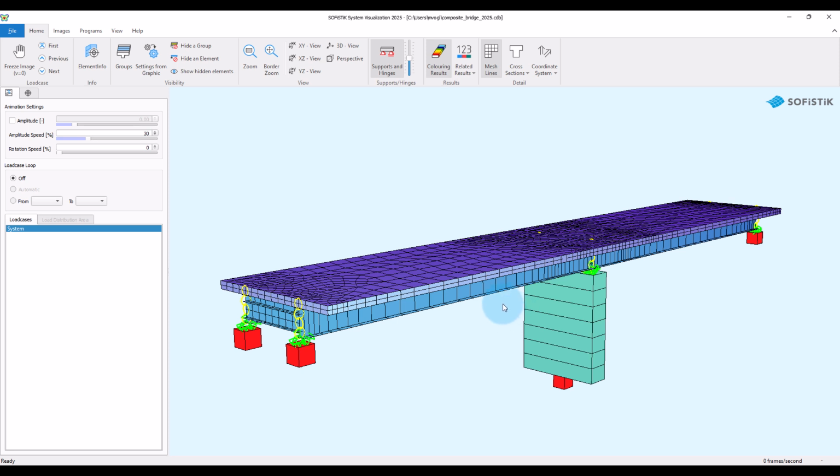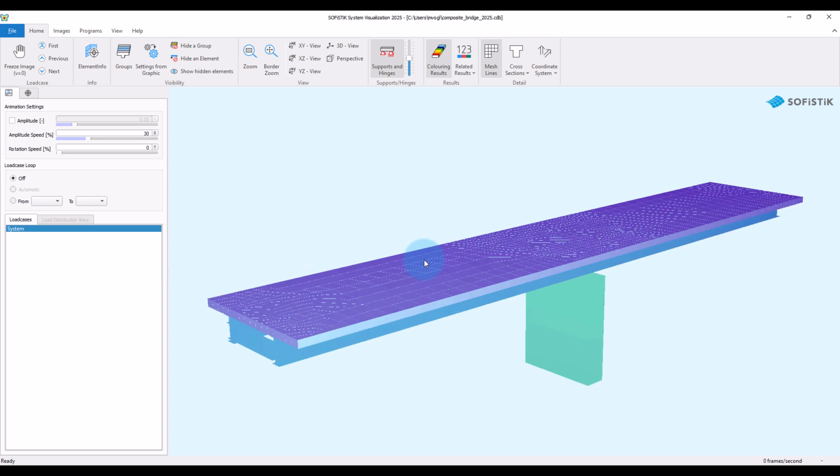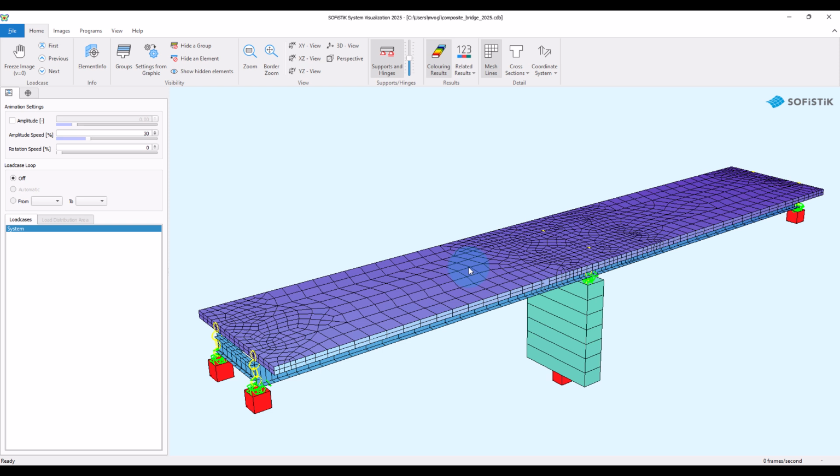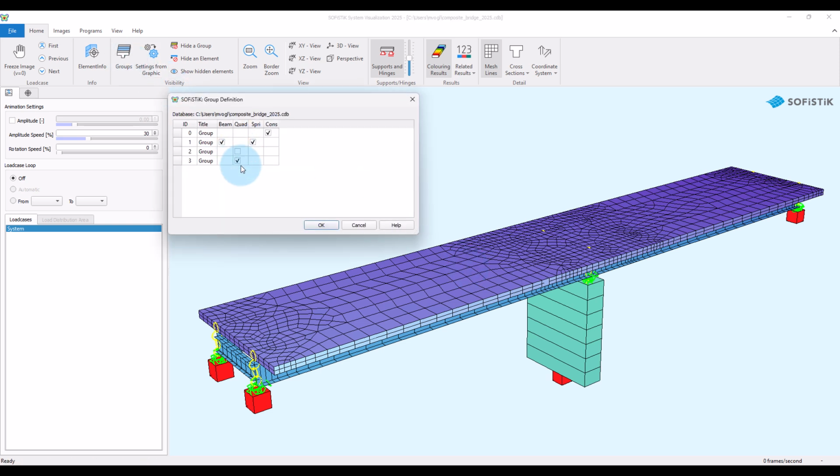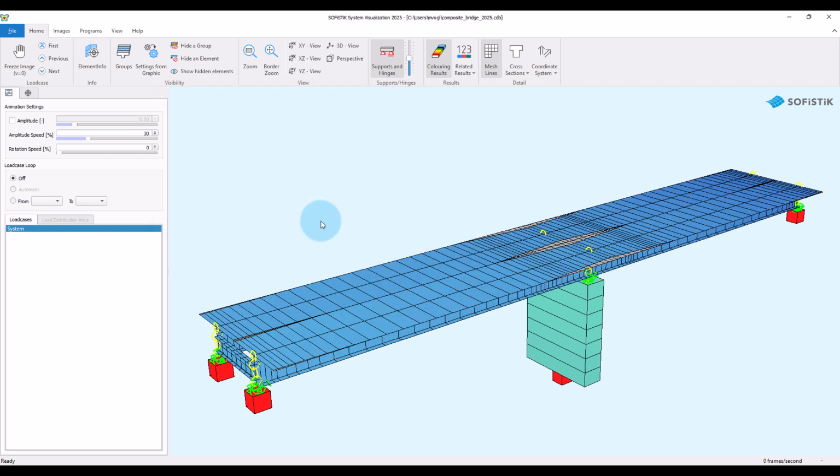The idea is, because we focus here on the design of the main girders, we need the area elements only to connect the girders and to apply and distribute loads in cross direction. Therefore, we will switch the stiffness of the area elements in longitudinal direction off. So the stiffness of the concrete in longitudinal direction will be represented only by the beam elements.